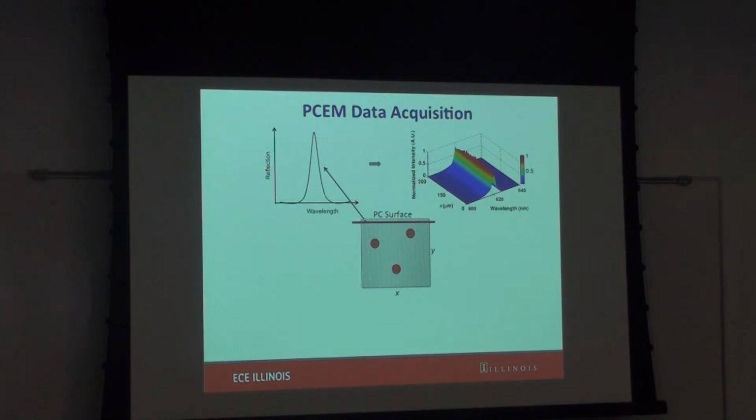We want the resonance to be relatively easy to measure at the same time. If it becomes really narrow, you may only get a couple pixels worth of reflection spectra out of your spectrometer, but we'd really like to be able to measure the whole curve. So we have a trade-off between resolution and ease of coupling light into it.